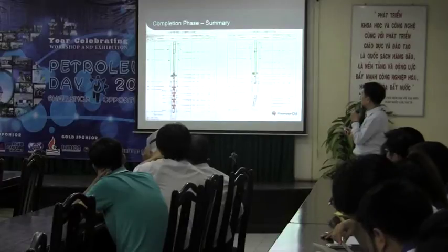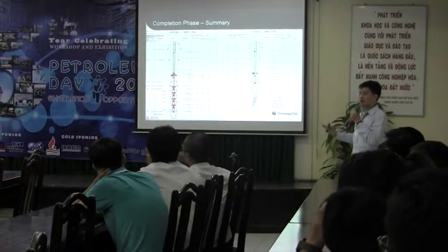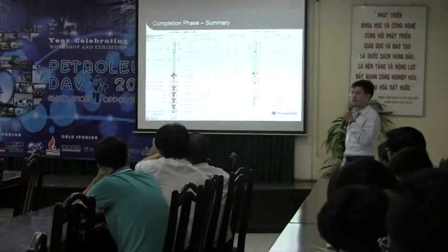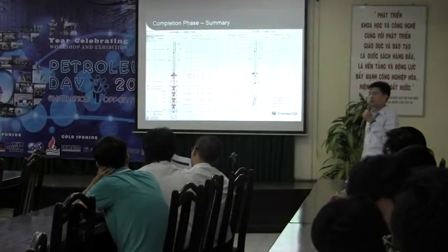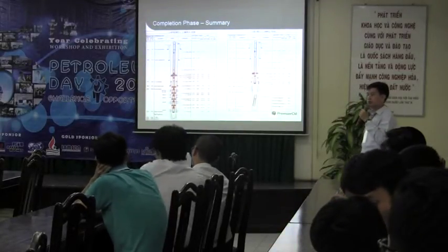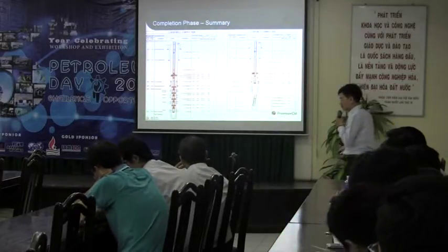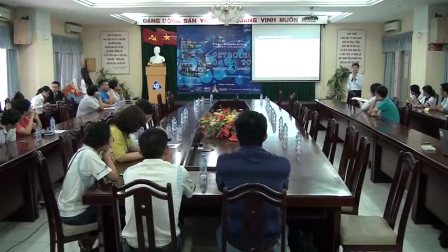After we finish drilling and set our casing, inclusive of the 7-inch liner, with cement behind the casing or liner, we move to the operation of well completion. Well completion is nothing but running a string into the well and connecting all the lines to the production line.